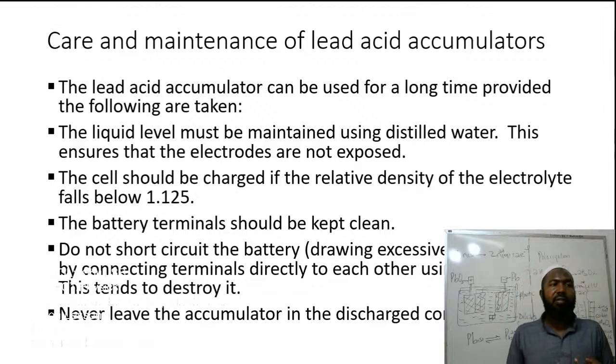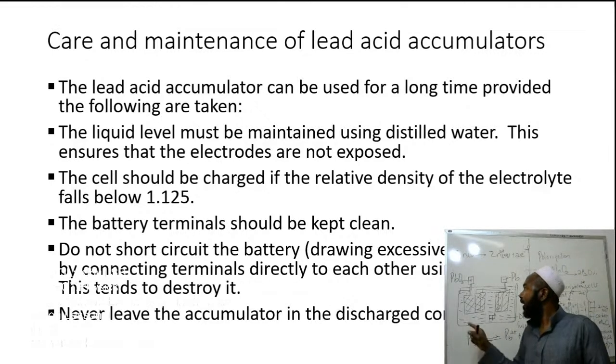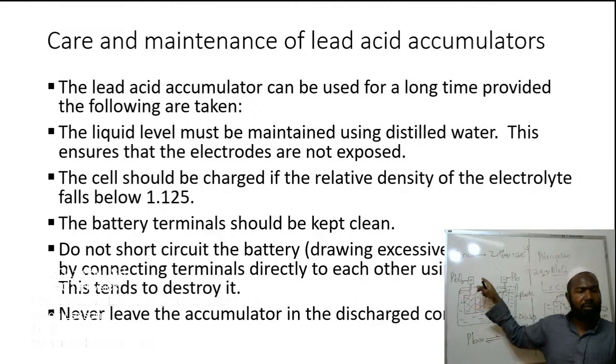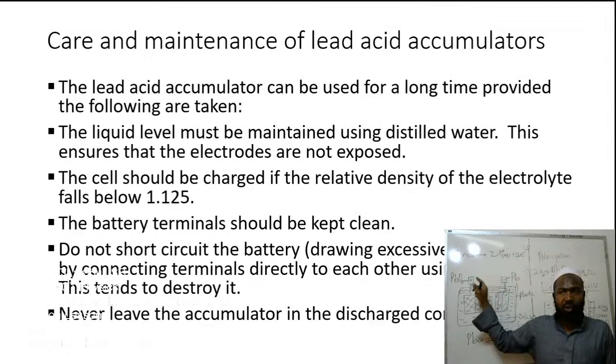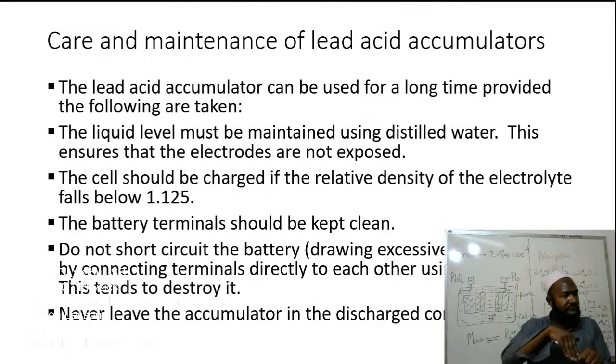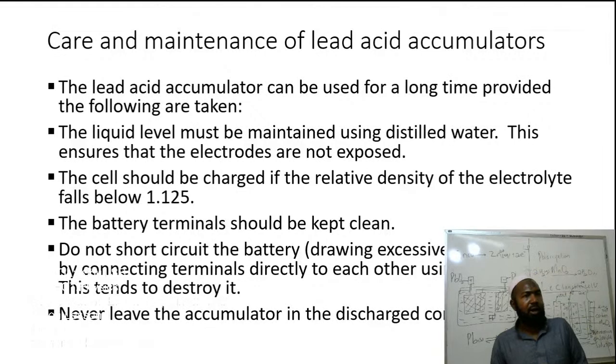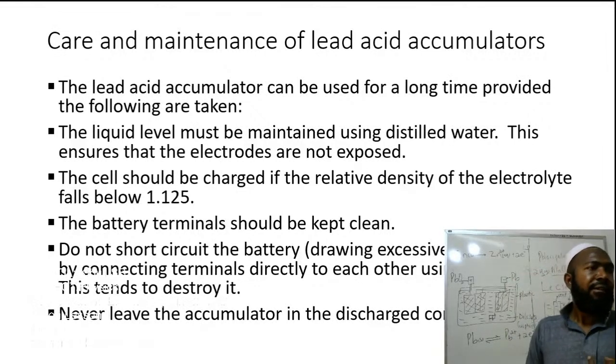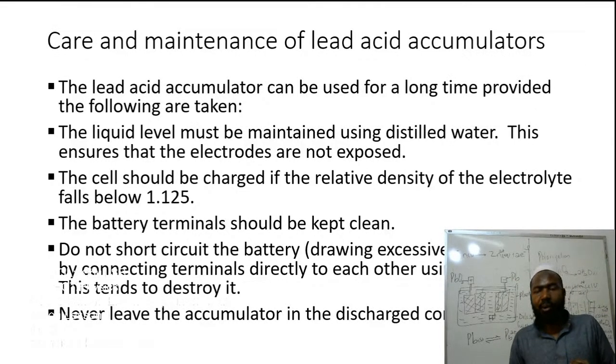3. The battery terminals should be kept clean. Sometimes you normally see a whitish film getting deposited on the electrode. You remove that white coating, which is a result of polarization. You occasionally brush it so that it is fresh for other charges.